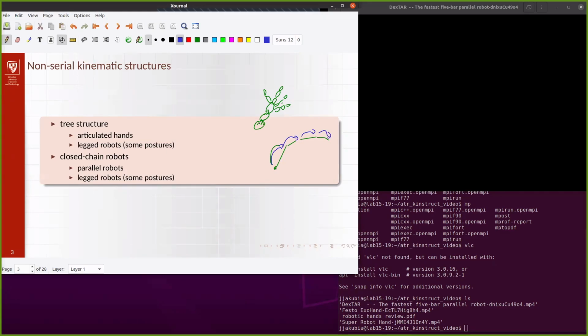It will partially work like that, but in fact we can treat each of the tips of the fingers as a separate effector. So we will have one kinematic solution for this chain, another one for this chain, and this chain, and this chain. So in fact we have 4 effectors and 4 different kinematic chains that we can consider.